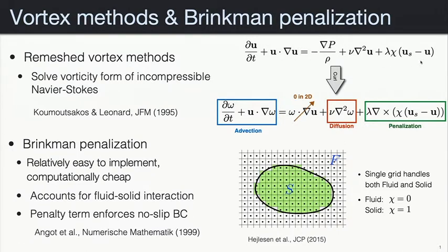What this forcing term does is, see, this is exactly the difference. So that's the expected solid velocity. This is the actual velocity at the grid. Okay. And when this difference is equal to 0, the forcing term turns off. If this difference is non-zero, the forcing term will do something, right? Let's see what it does. So let's say the u here is slower than the solid u should be. This term is what? Positive or negative?